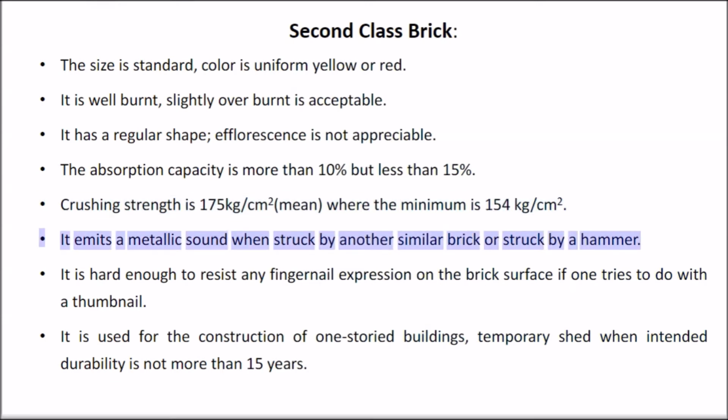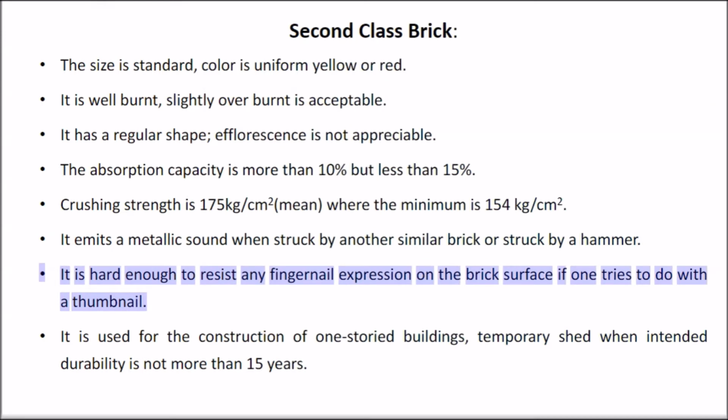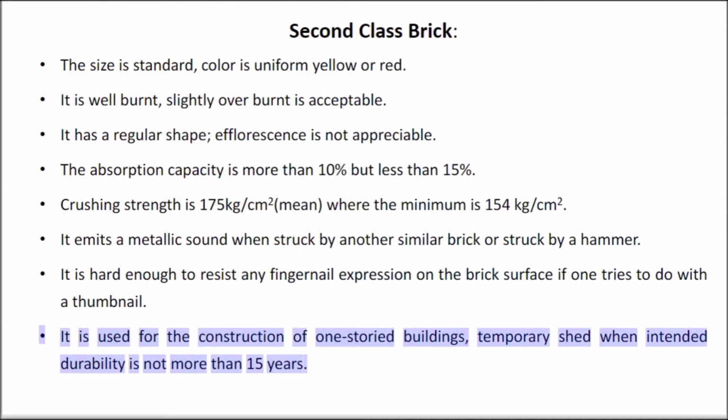It emits a metallic sound when struck by another similar brick or struck by a hammer. It is hard enough to resist any fingernail impression on the brick surface if one tries to do so with a thumbnail. It is used for the construction of one-storied buildings and temporary sheds when intended durability is not more than 15 years.